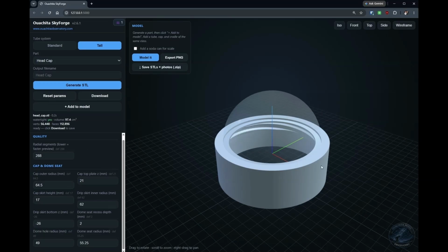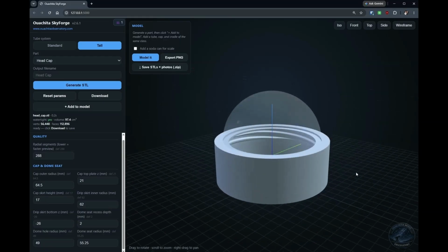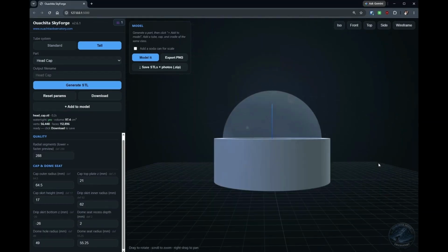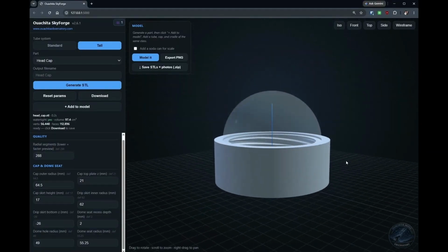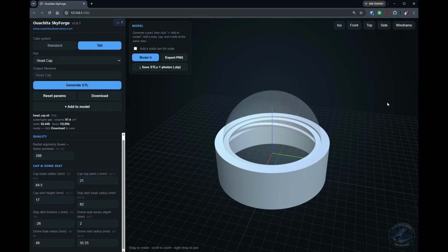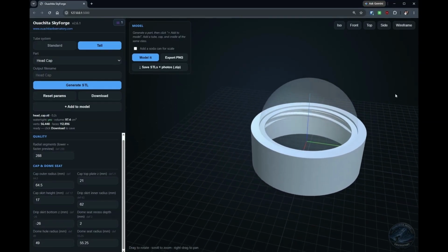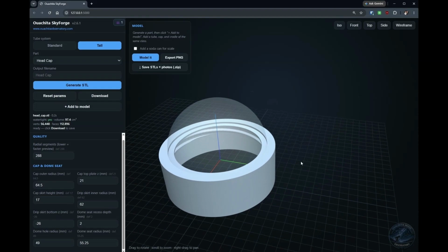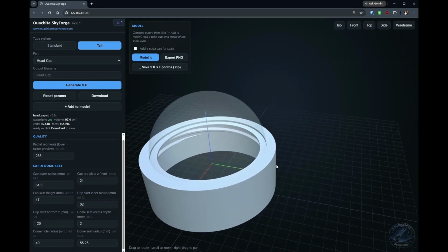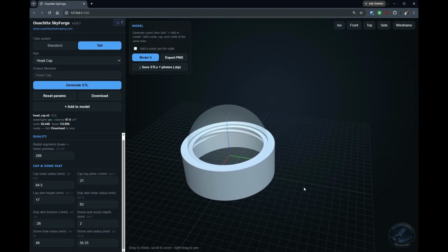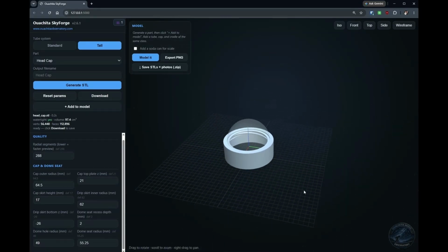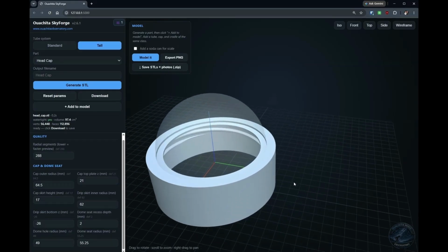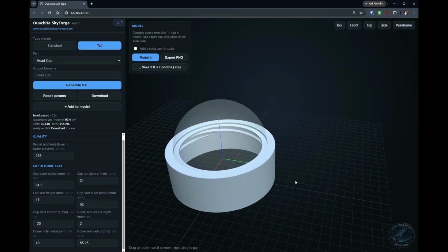Let's look at the interface. You have ways to move these things around. If you left click, it's kind of a free view. You just click and drag, holding the left mouse button, moving up and down. You can see how I'm just moving my mouse around. If you want to pan, you just right click. I'm right clicking the mouse, and this is a pan left and right. If you want to zoom in, just scroll your mouse wheel, or hold your mouse wheel, the middle mouse button, and then drag forward and back. The slow zoom is just rolling your mouse wheel. If your middle button is a wheel, just scroll back and forth like that.